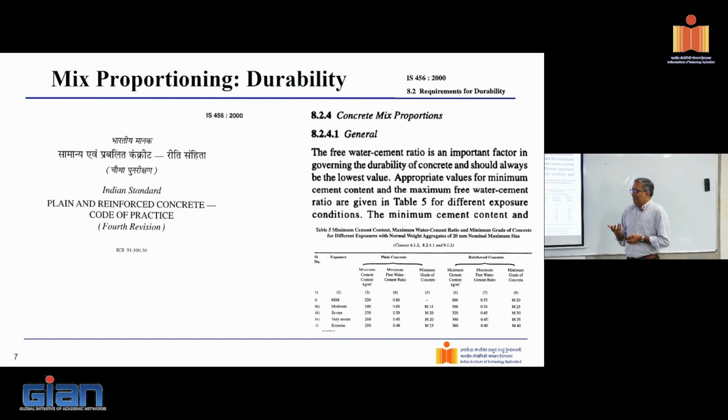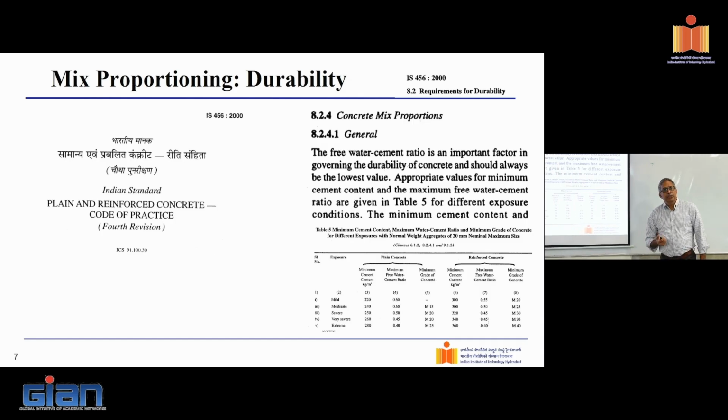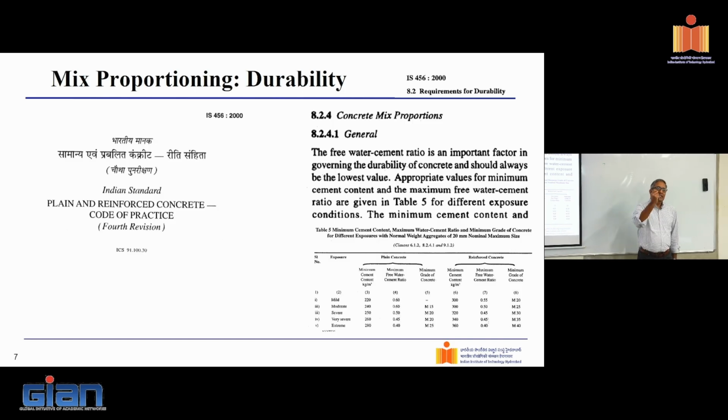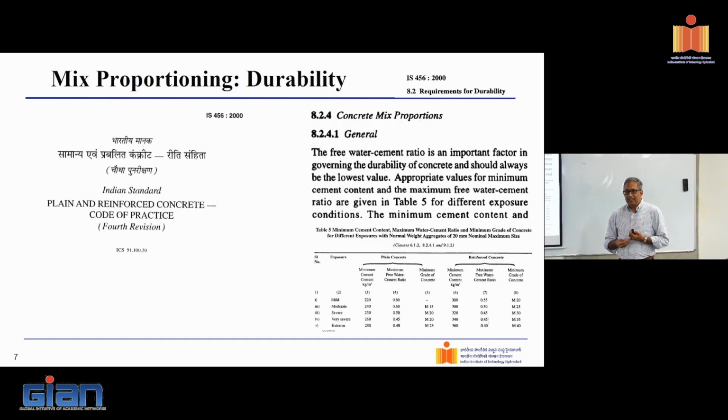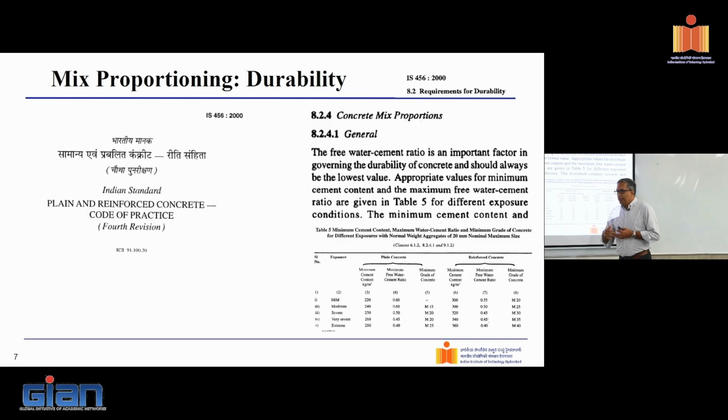The understanding is that if you look at what makes cement paste denser, you reduce the water to cement ratio. What you get is something that is less porous, right? And that will basically prevent ingress of the deleterious materials, which could be chloride ions or sulfates from outside. So if you're looking at durability concern for concrete, the primary concern is to keep the external agents outside, not let them enter into concrete. How can I do that? Well, aggregate at some level are inert. They're not going to allow things to get in. How will things get in? Through the cement paste medium that is in the concrete. How do you control that? With the water to cement ratio.